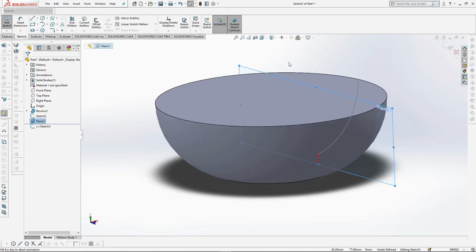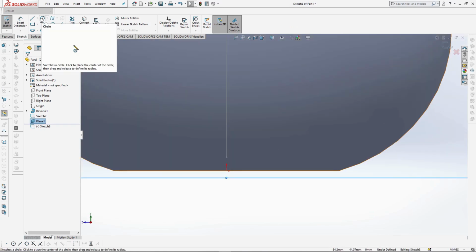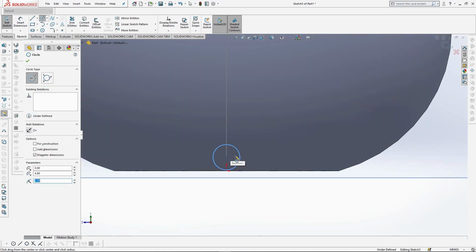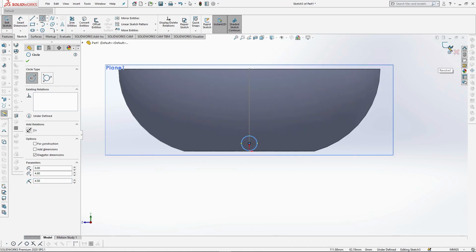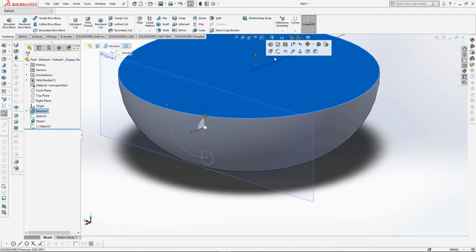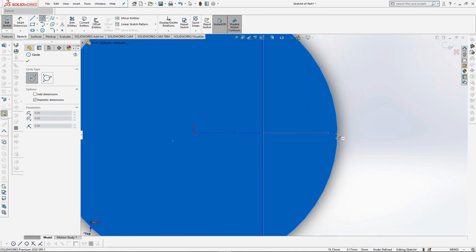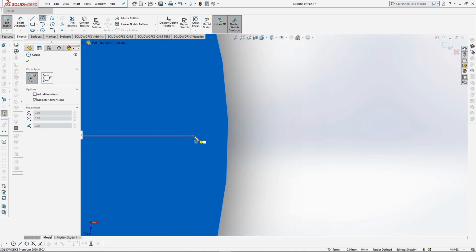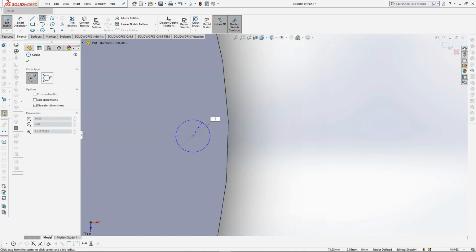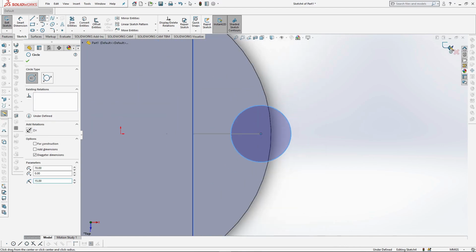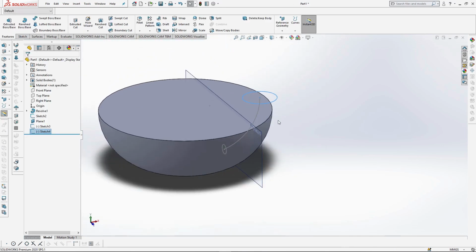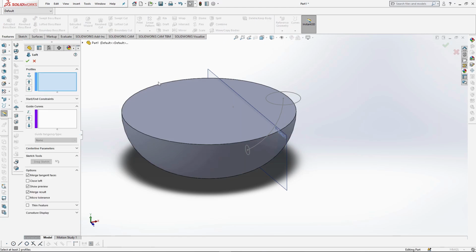From here, I can use the new plane to create a new sketch. Viewing the new plane normal to, sketch a 9mm circle from the end point of the guide. Close this sketch and start another new sketch onto the top face of the revolve. Use the circle again and sketch a 30mm circle here. Then close this sketch. With the two sketch profiles done, select the Loft tool under Features. Clicking into the Profiles box, select the two circles.